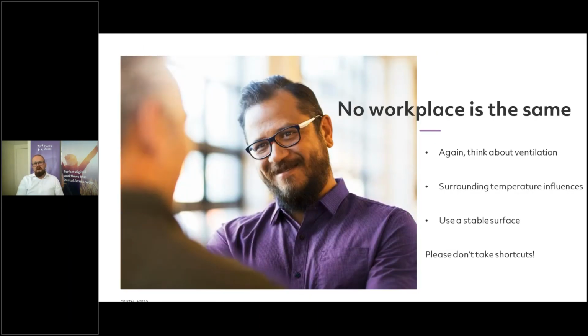One of the things I really want to mention also is no workplace is the same. Again, think about ventilation. Every room ventilates differently. You want to be in a clear, clean environment. The surrounding temperature also influences your print. Most of the printers have a heating system, so they say between 30 and 35 degrees. I heat up my liquid and it flows really well, and with that I can do a successful print.